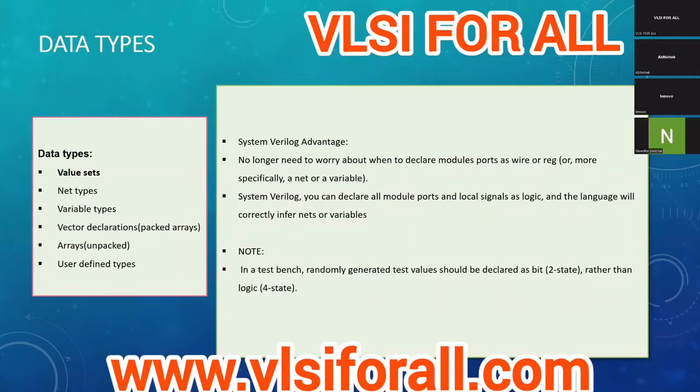The only thing to remember here is bit is 2-state, and logic is 4-state. So wherever you want to use 4-state, define it as logic. Wherever you want to use 2-state, define it as bit. Nothing else we need to care about when we are using SystemVerilog. No need to care about net, wire, or res, anything like that.